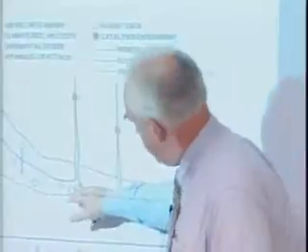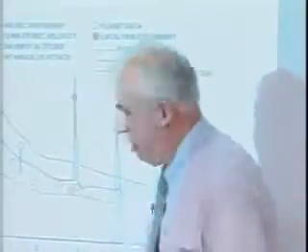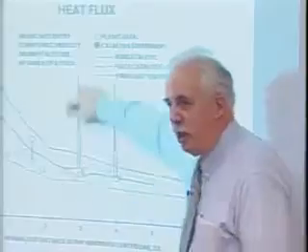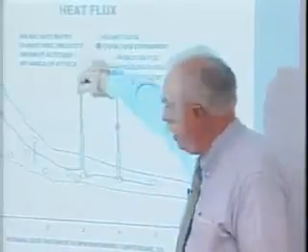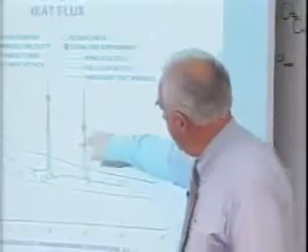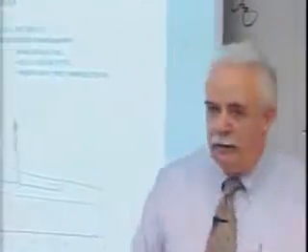If the whole vehicle was like that, the heating would have been up here. But since it was just a tile, the boundary layer comes along here, all of a sudden, boom, it gets hit with a different boundary condition. Okay, we've got all those atoms, and they see this catalytic surface, the heating goes way up, okay, and then relaxes. This is the computation, and there's the measurement.